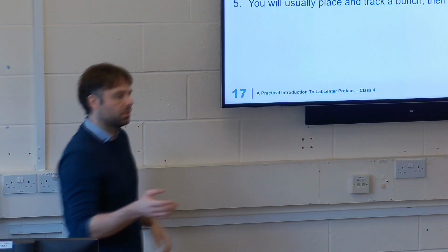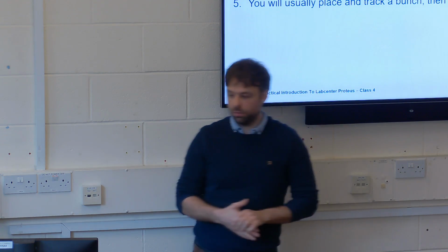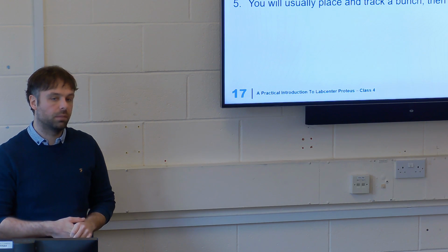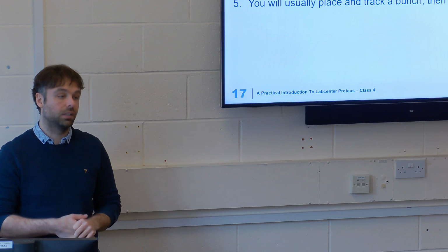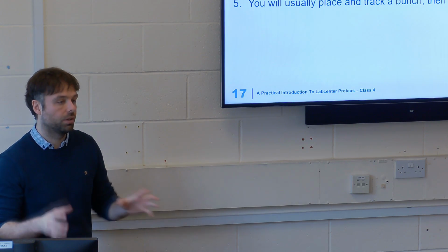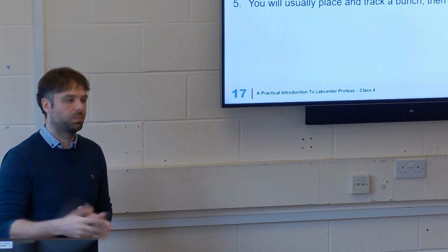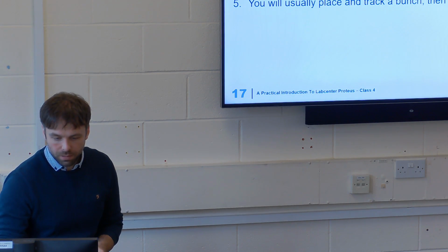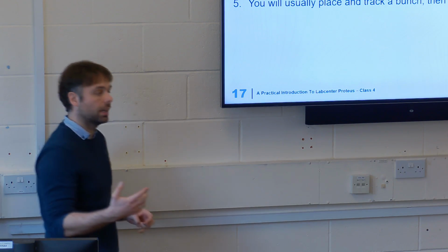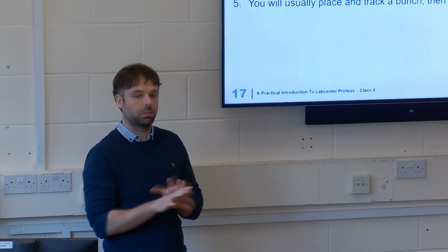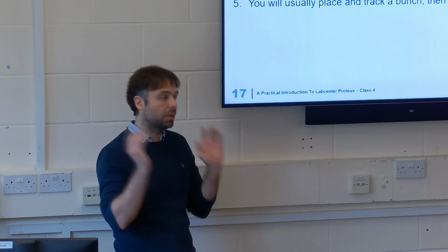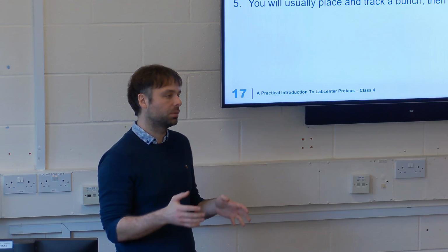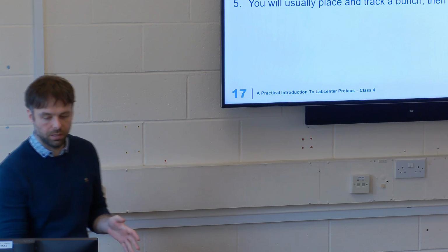We're not going to do much design for EMC yet, but I think that we should start to look at that. And as and when we start to test our circuits for EMC, you'll start to see these things that I'm showing you come into play, because you'll test the circuit and it'll fail, because I've done it. Placement is paramount. Untangle the routes before tracking. The placement of the components is one of the most important things you can do on a PCB. Get the placement right, and the tracking becomes a really enjoyable job. If you don't get the placement right, the tracking is a nightmare.